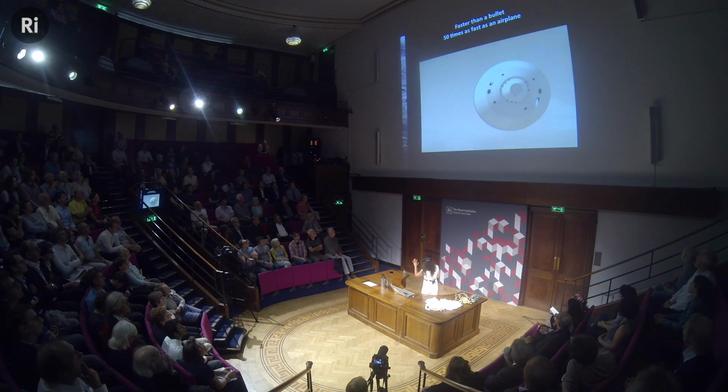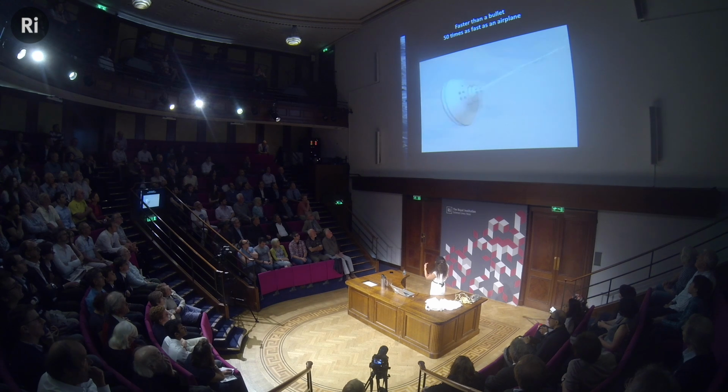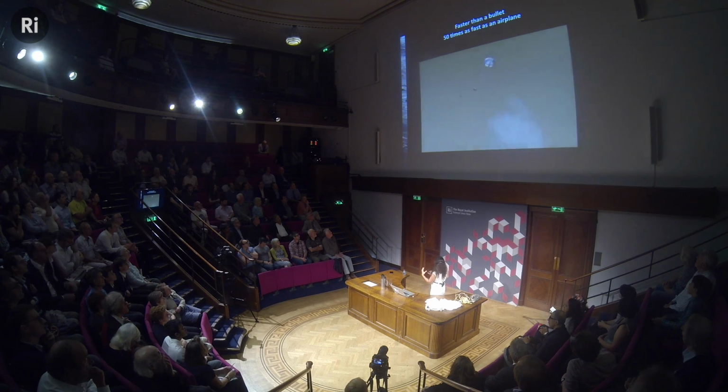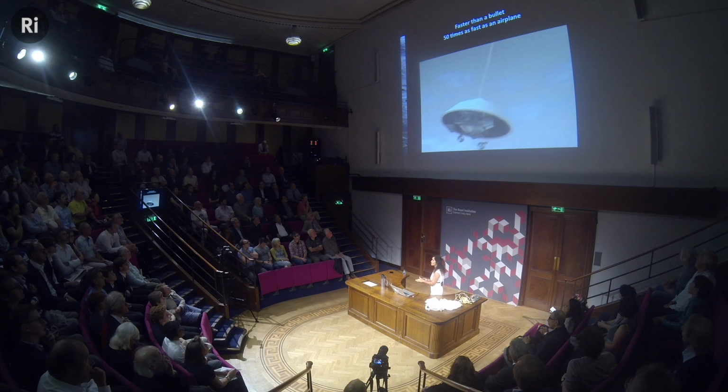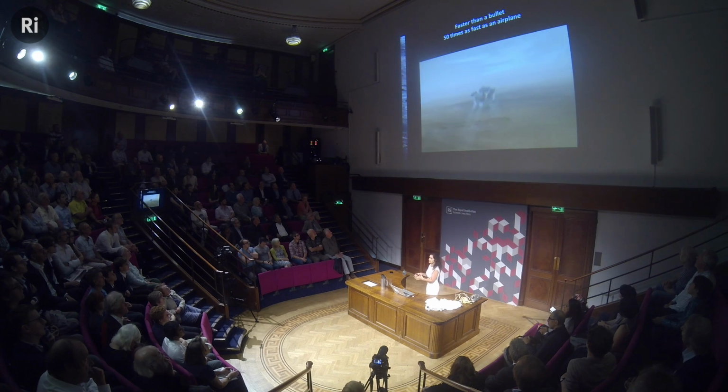So this is the entry descent landing sequence. Landing up through a planetary atmosphere utilizes the atmosphere to produce aerodynamic drag. So you come in at 13,000 miles an hour. You decelerate roughly from 13,000 miles an hour to around 1,000 miles an hour on a heat shield. You then decelerate from 1,000 miles an hour to around 250 miles an hour on a parachute. Then you actually can't go any slower on the parachute. You've hit terminal velocity. And so at that point, you actually cut the parachute away. And then you descend the rest of the way, slowing yourself down using retro rockets, firing towards the ground. That's the way you dissipate the energy.